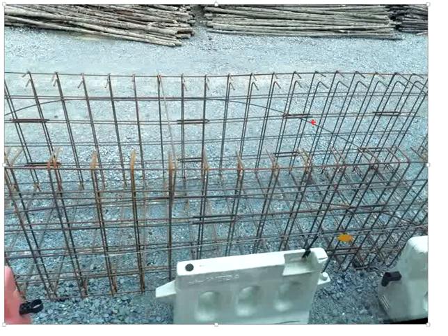Another interesting thing is this reinforcement bar, which is placed in some form of arc along the spans of the drain. To be frank, I do not know what is the function of this reinforcement bar. By looking at the location of this reinforcement bar, it seems to be functioning as the compression reinforcement bar, as the compression strut of the concrete drain.